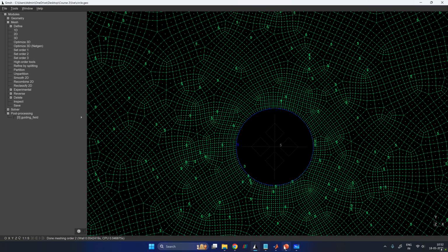In this case, I will be showing you the shape functions for quads and triangles, and I'll also be giving a shape library for quads and triangles up to the third order. But I will really be using only triangles for the coding purpose, and going from triangles to quads is very easy if you have the mesh. You just have to swap the shape library and take care of the indexing. I'll show you how to do that. It's a very simple operation. So let's begin by deriving the shapes.